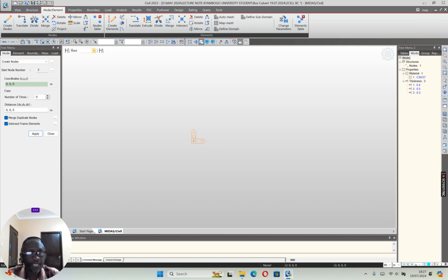So with that, I'm able now to say, okay, fine, I have gotten this, so let me offset the width, and it is a double cell, where the wall thickness is 400 millimeter. Then the interior is 4 meters and 300 and 4 meters and 4. So center to center is actually 4. The 150 and 200, that is 350, so 4.35. So I'm able to translate.